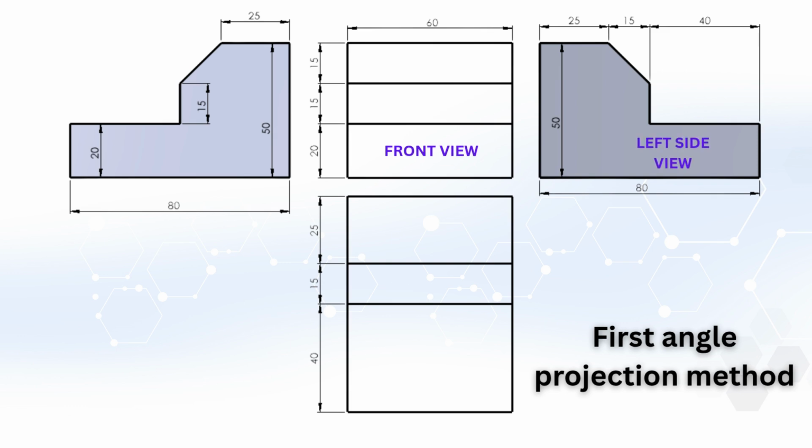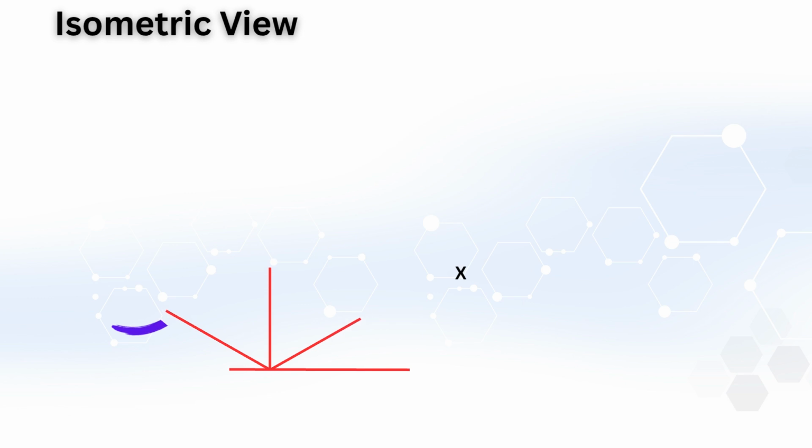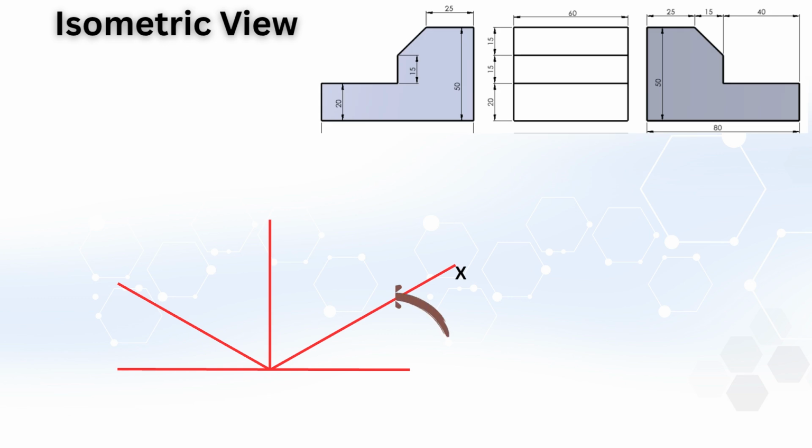According to the viewing direction, the front view corresponds to the YZ plane, while the side view corresponds to the XY plane. The drawing starts from the side view, which is placed on the XY plane. According to the given orthographic views, the total length of the object is 80 mm, and the total height is 50 mm.